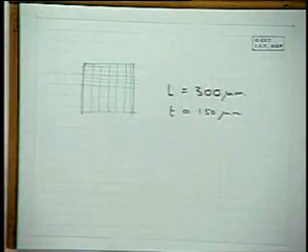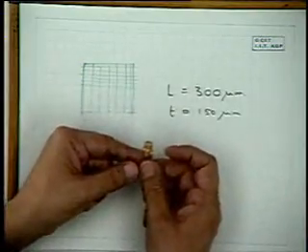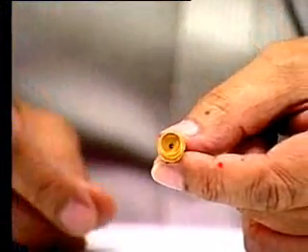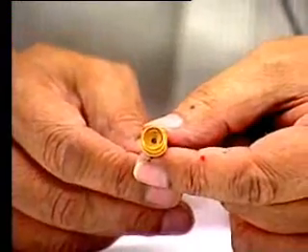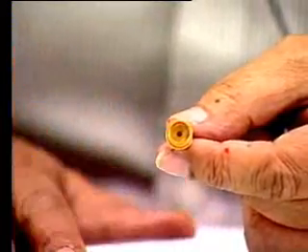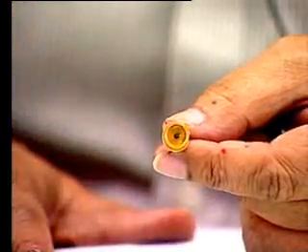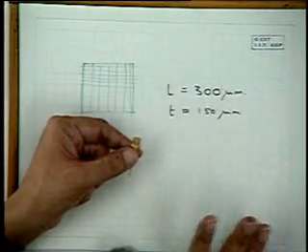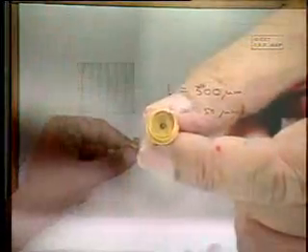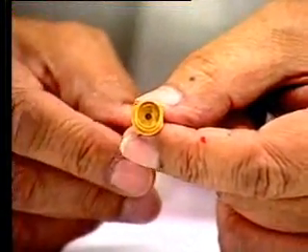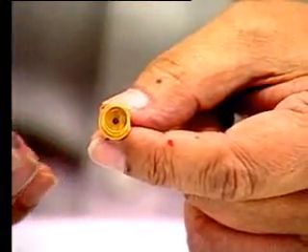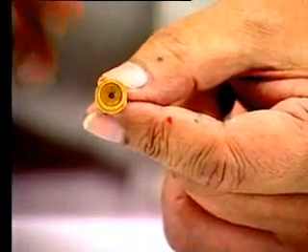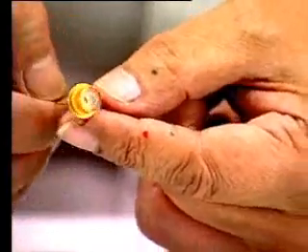I have a small device here, which I don't know if you can see. You can see most of it is a massive heat sink. This, incidentally, is a device that was made in 1977. Okay, RCA, double heterojunction. The threshold current of this is 75 amperes. So as a result, this device has never been used. The power supply required for this is 200 nanosecond pulses at 75 amperes threshold current. It will give you some 20 or 30 watts output. And you find right at the edge, there's a little tiny device mounted on the edge. You can come up later and see it. And the rest of it is all a heat sink.